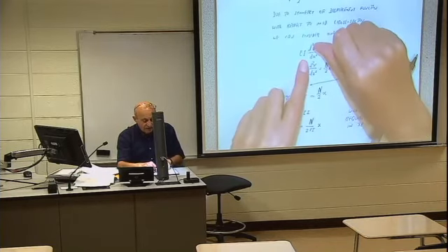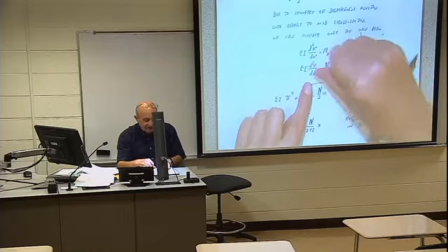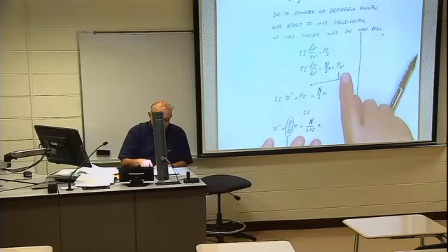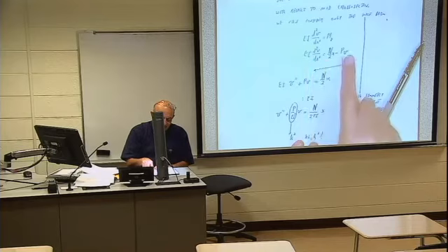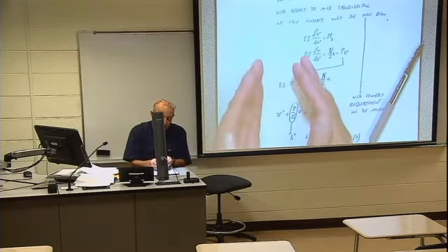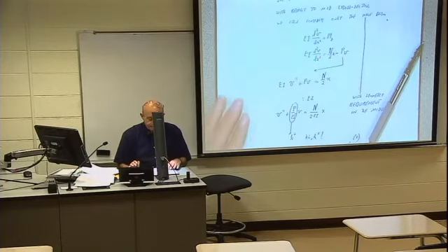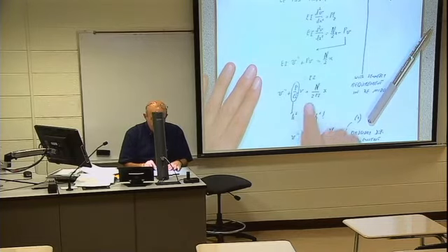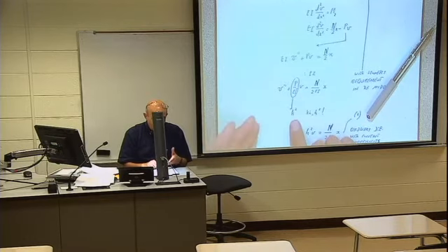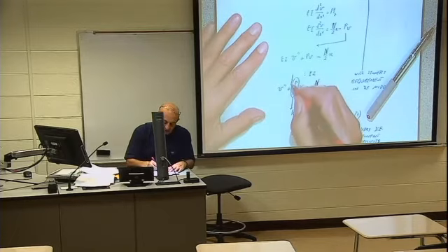So, EI d2v dx square equals Mz. Mz equals N over 2 x minus PV. So I'm writing down EI v double prime, I just rewrote this, plus PV, because I transfer this unknown function to the left side to have unknowns together and knowns together. I divide again by EI. I get v double prime plus P over EI v equals N over 2EI x. That P over EI is k squared. I denote it again, that is our notation.